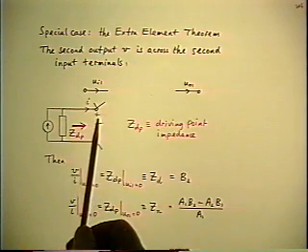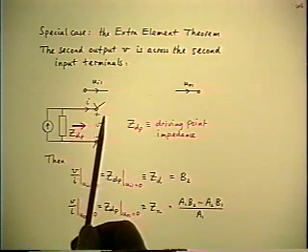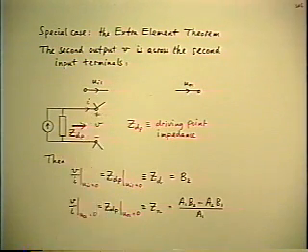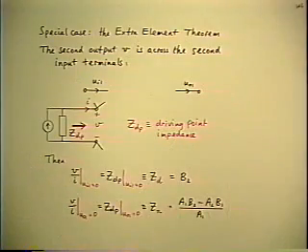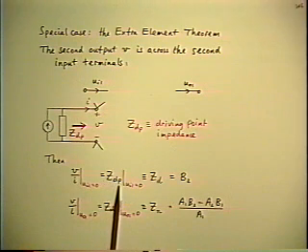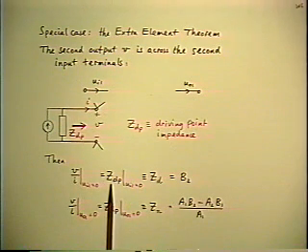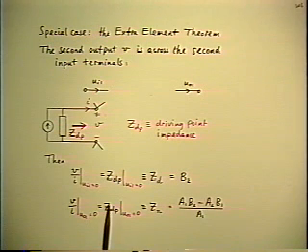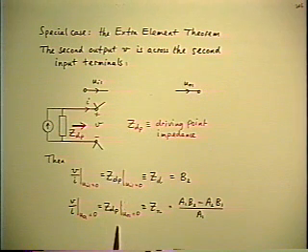Because it is now a self-impedance, because it's the ratio of a voltage to a current at the same place. It's what the circuit theory people call a driving point impedance. A driving point impedance is simply the impedance looking into a linear system when you apply a drive at that point. And so the notation is ZDP, driving point impedance, but you still get two different values for it, depending on what the hidden input is doing.